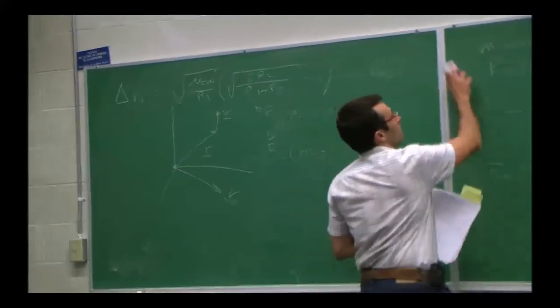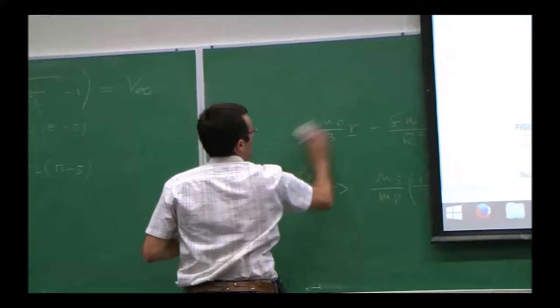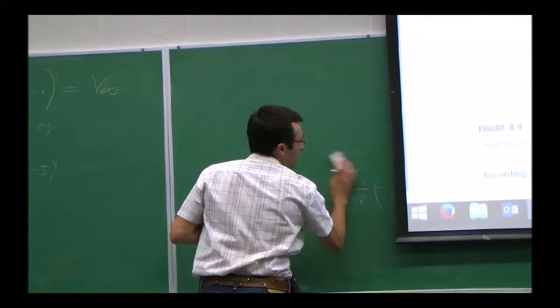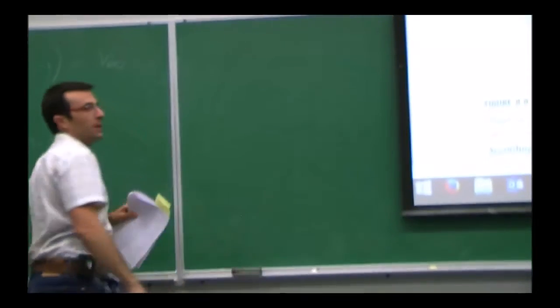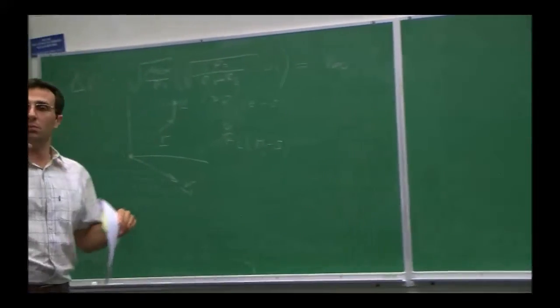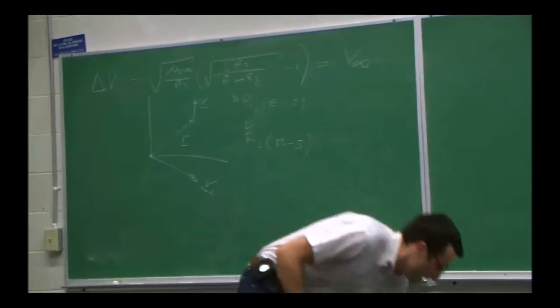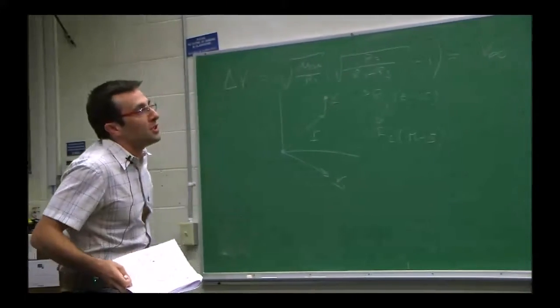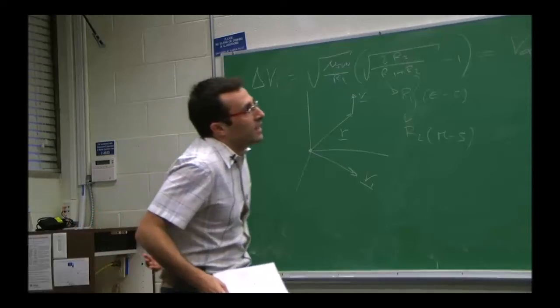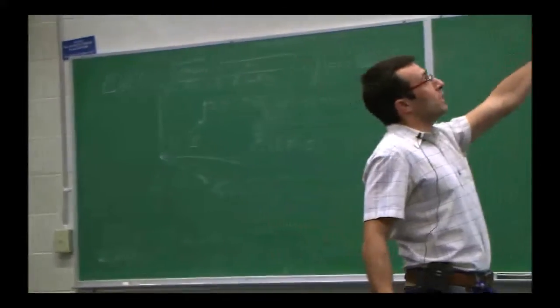So the steps are the following. I'm just going to give you the steps here because I am not using anything that we have not seen before. Remember when we finished the chapter about Keplerian orbits and there was that summarizing table at the end with a bunch of formulas for the circle, parabola, etc. That's exactly what you use here. There's nothing special. It's just that now someone is giving you the V infinity.